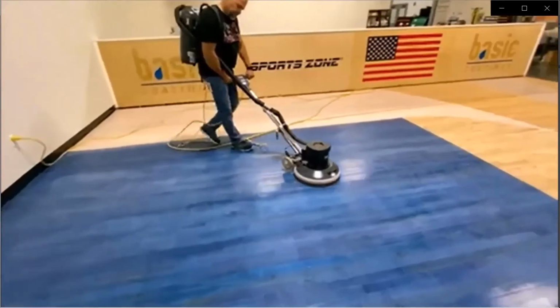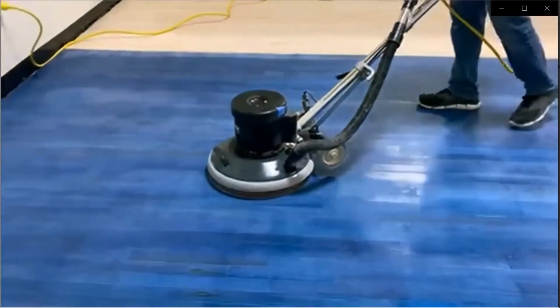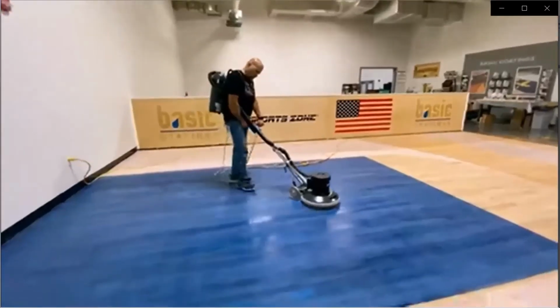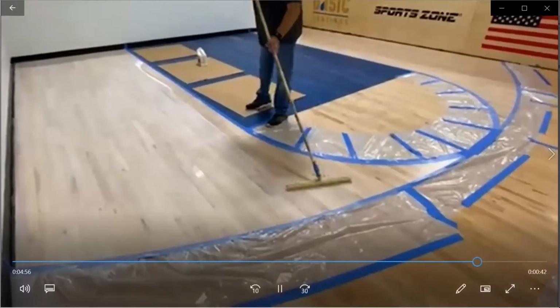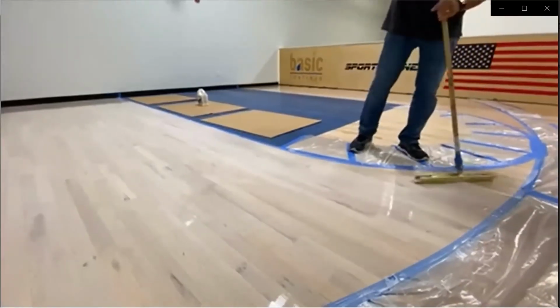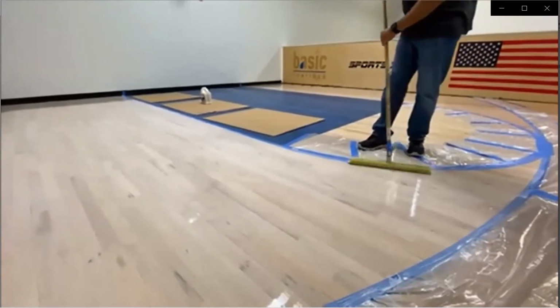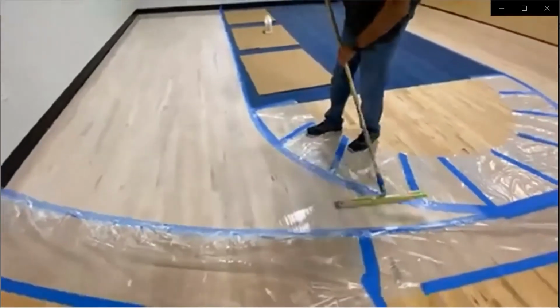It is important to abrade the sealer coat prior to applying tinted finish. Abrade the sealer so that the sealer coat is not shiny. It needs to be dull to achieve a proper bond. Turns and feathering out will show if not done properly. Avoid making turns when possible by going with the grain and pulling off onto masking material. Do not apply more than 2 water-based products in a single day.